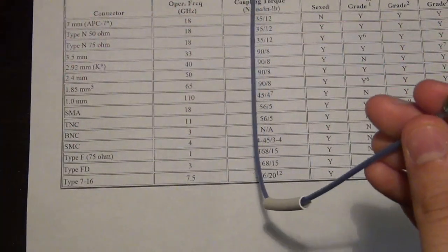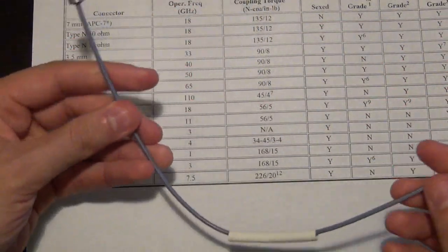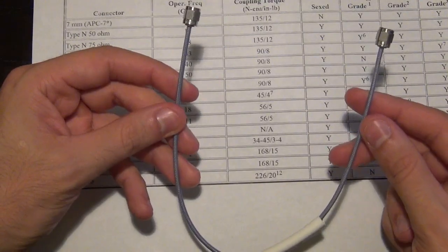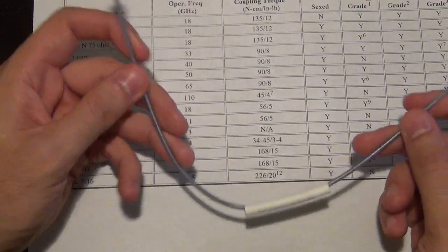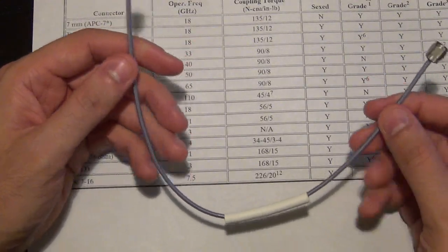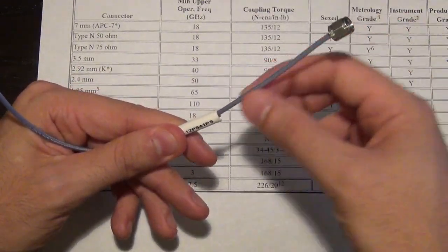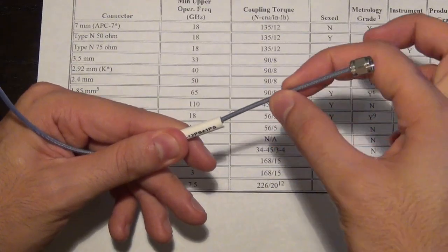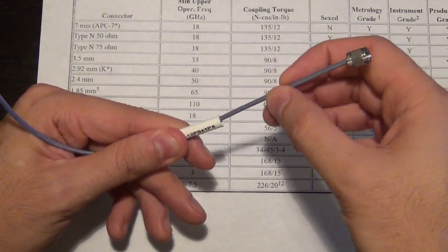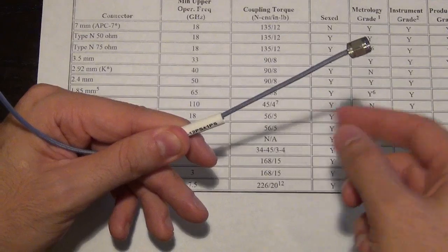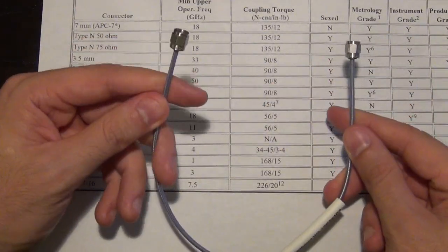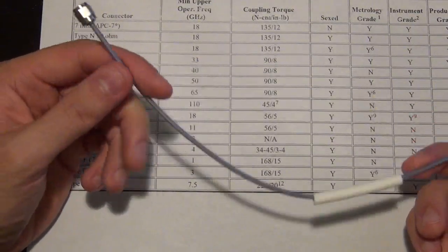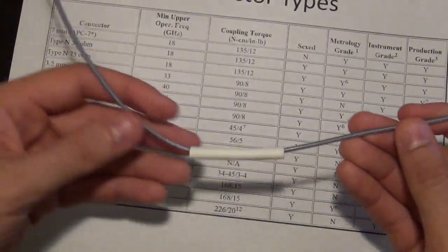So be extremely careful when you do that. Another thing very important about millimeter wave and microwave cables is that you should never bend them too much, and you should never bend them unnecessarily, because as you bend them, the characteristic impedance of the cable can actually change. If the bend radius is too tight, you can damage the dielectric, you can damage the center tab, and the characteristic impedance will change, and they will be no good anymore for measurements.